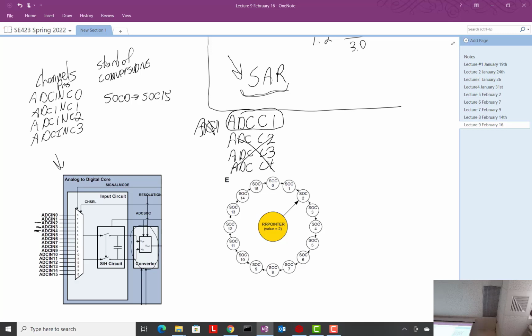Some of the things you read with 3-phase motor control are not very critical in time. But when you're trying to drive the correct current through this 3-phase motor, it's really important to sample the current at specifically the right time and consistently doing that. And so you'll see if you read through this, there's ways to prioritize some of these SOCs over other ones.